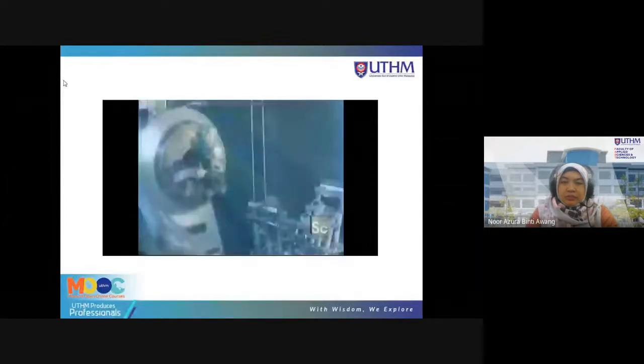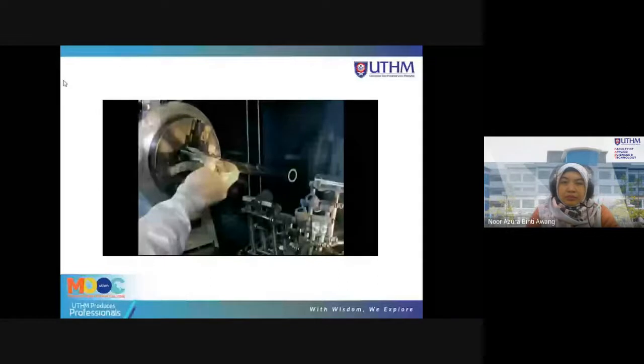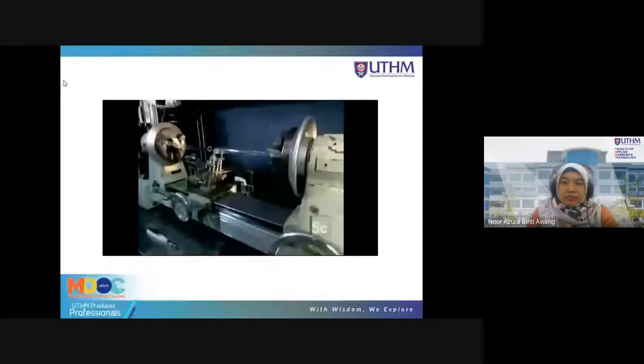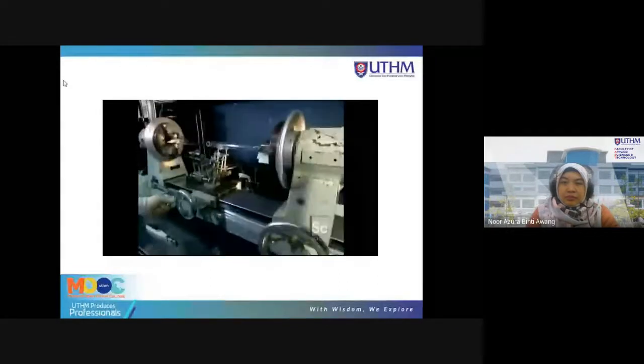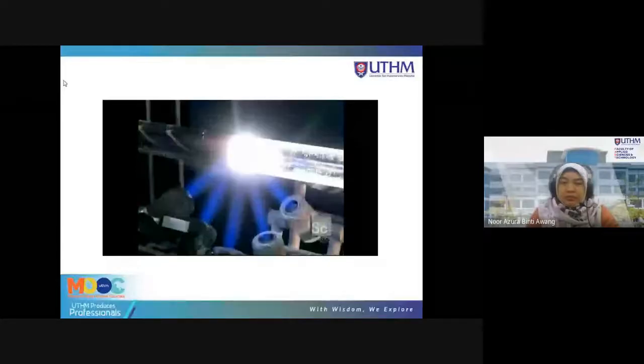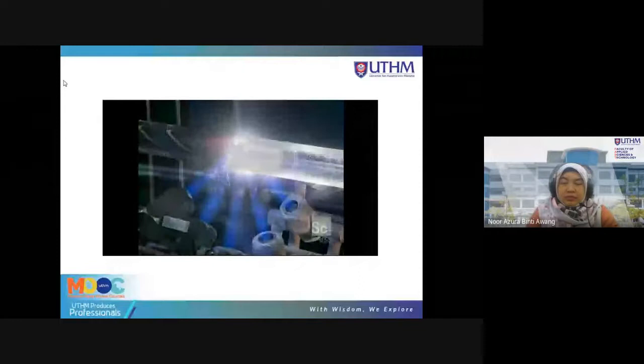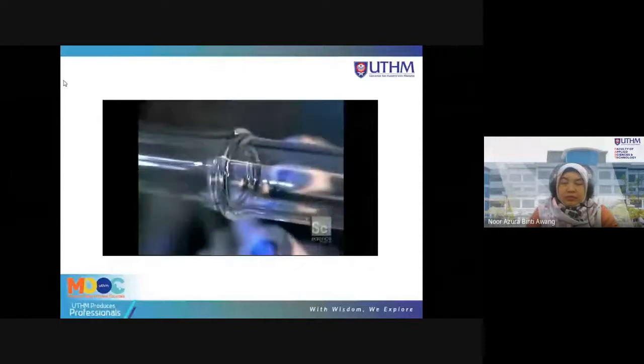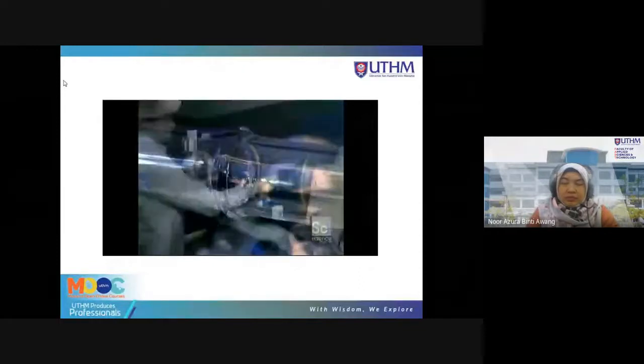Then they set a tube into each end of a lathe. As the tubes spin, they're heated with a hydrogen-oxygen flame. When the glass turns white, it's getting close to peak temperature. At about 3,500 degrees, the two tubes fuse together. They put this new longer tube onto another lathe.